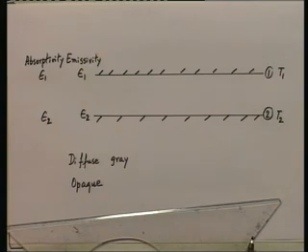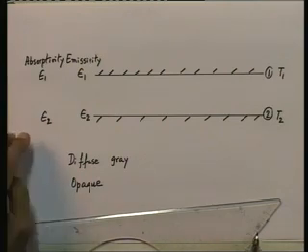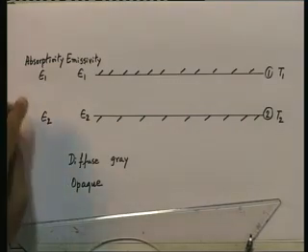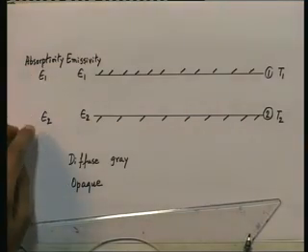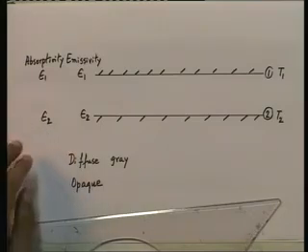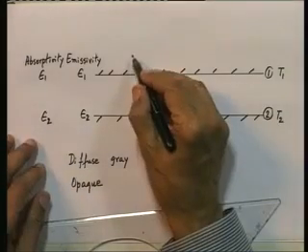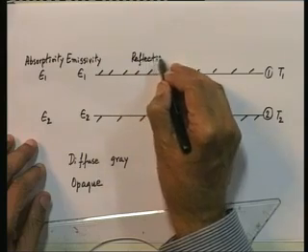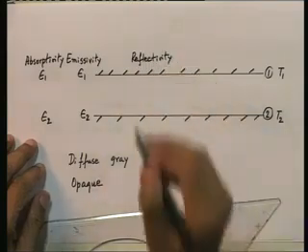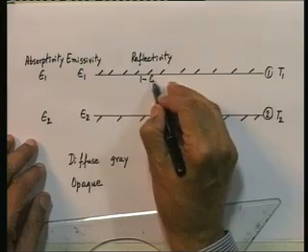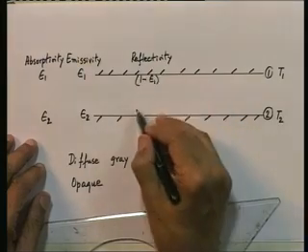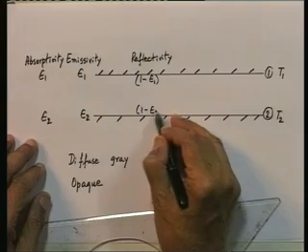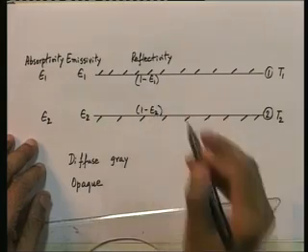If they are opaque, it follows that the reflectivity of these surfaces will be 1 minus epsilon 1 and 1 minus epsilon 2. So, let me write that also. The reflectivity of these two surfaces, this one will be 1 minus epsilon 1, this one will be 1 minus epsilon 2, because they are opaque.